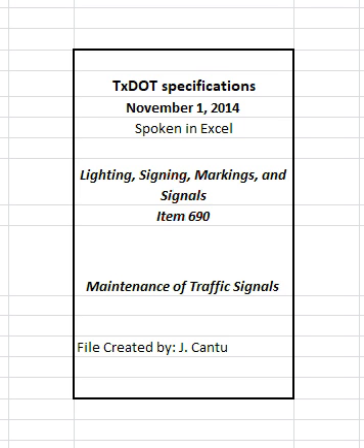4.22 PVC weatherproof enclosures. Install, remove, or replace 12 x 12 x 6 inches PVC weatherproof enclosure at locations shown on the plans or as directed. Only use enclosure for reconnecting or terminating traffic signal cables at the top of a timber or steel strain pole which has been replaced or reinstalled due to accidental knockdown. 4.23 LED lamp unit. Install, replace, or remove LED optical unit in accordance with item 682, vehicle and pedestrian signal heads, as shown on the plans, or as directed.